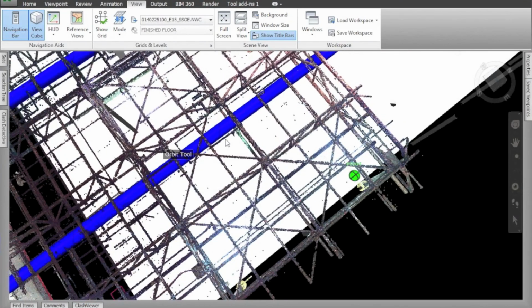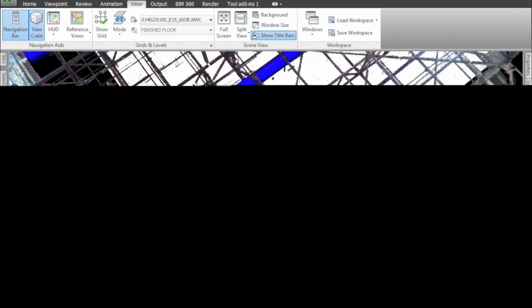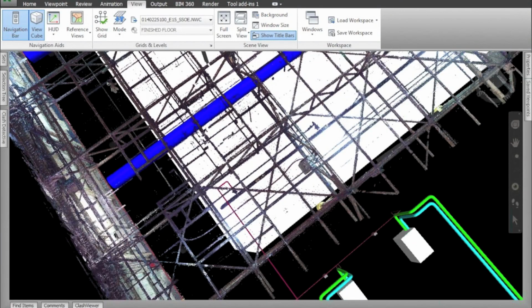In this Navis view, if it's a relatively flat and straight pipe, we'll look at it like you're looking right down the barrel of a gun. Straight on, make sure your ortho's on, and then I prefer, as I said, the rectangular tools. Fence is good here and there, but try to use it sparingly, just to get within there. And then you can always deselect if you've selected too much before assigning that pipe to a demo region.